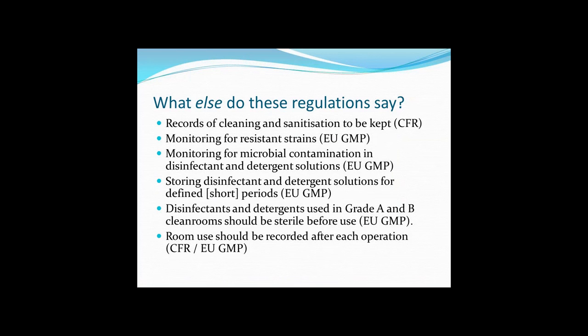Then there are aspects about ensuring that the disinfectant and detergent solutions are themselves not contributing to the bioburden. So in EU GMP grade A and grade B areas, there's a requirement for those solutions to be sterile, either being brought in sterilised by, say, radiation, or sterile filtered in. Then there is the way that the disinfectants and detergent solutions are stored, and this needs to be defined, and generally there's an acceptance that this is for a short period.